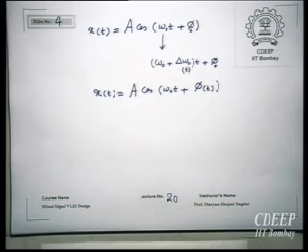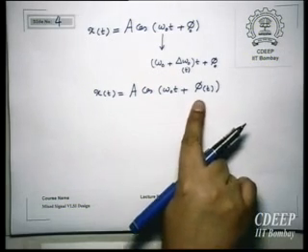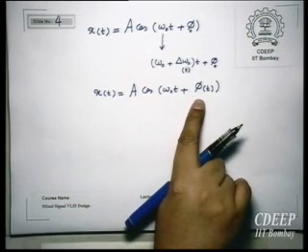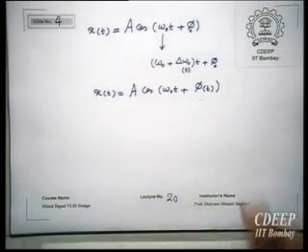Actually, due to flicker noise, it changes again with time very slowly. But this time, in contrast to temperature, it's not a predictable value. It's not a deterministic value. So because of flicker noise, we have a random but low frequency variation with respect to time. Due to temperature, we have a deterministic variation.